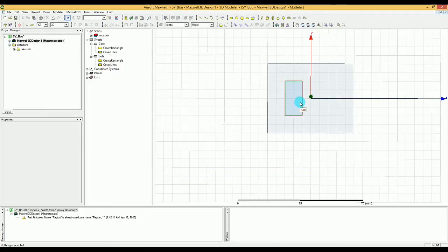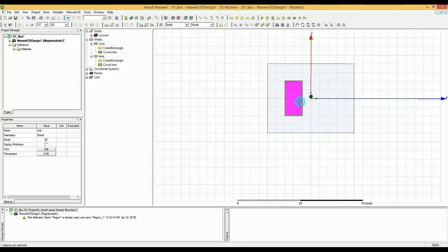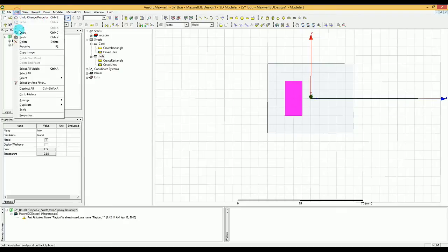So now you want to duplicate that, so you can use the mirror to just mirror it on the other side, since everything is going to be symmetric at the end of the day. So you select it and you go to the edit, and I'm going to use the menu here, and over there you select duplicate, and inside the duplicate you want to select the duplicate as a mirror.